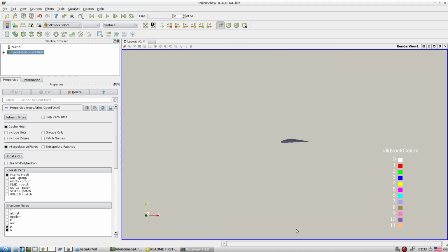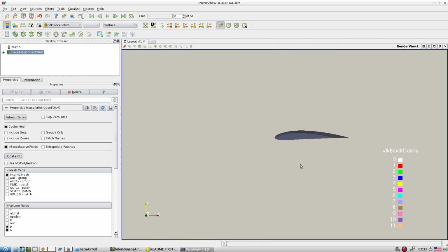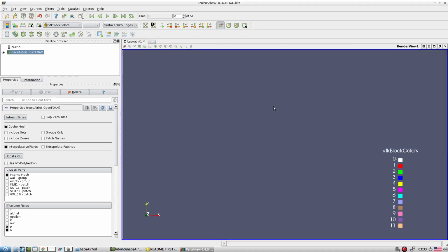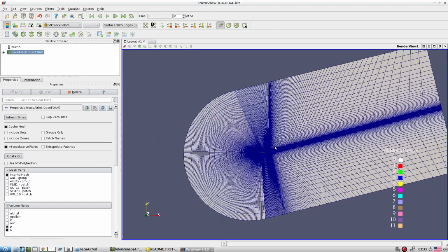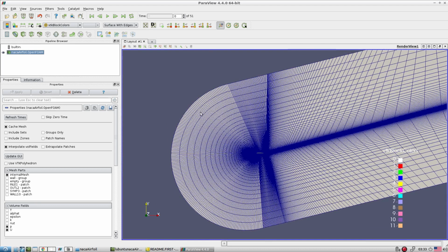Either you change the angle of attack by changing the geometry and retain the flow direction parallel to the x-axis, or you can change the flow direction this way and change the angle of attack. That is the idea. Now mesh size, we have pretty fine mesh in this area. That is what we have at present here in this direction. Now let's try to look at the result, because I already simulated it.